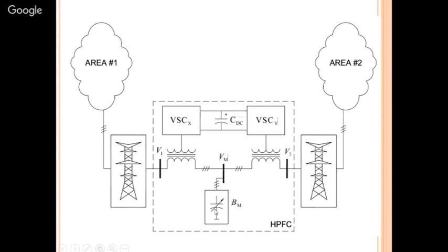Similarly, this is nothing but your thyristor controlled variable impedance device. By controlling the firing angle of those thyristors which are connected in anti-parallel, you are able to provide the variable impedance, which in turn provides the reactive power compensation. So those principles which we have studied in the last 2 days of the various devices like SVC, STATCOM, etc., are applicable here.